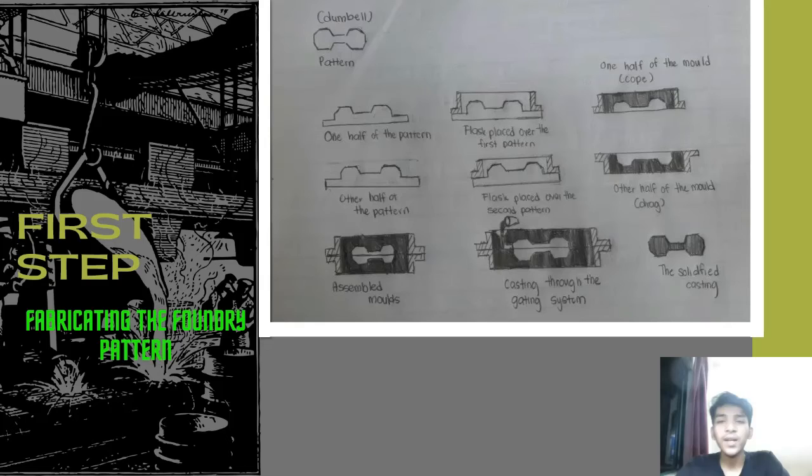The first step in the sand casting process involves fabricating the foundry pattern, the replica of the exterior of the casting for the mold. These patterns are often made from materials such as wood or plastic and are oversized to allow the cast metal to shrink when cooling. They are used to create the sand mold for the final part and can potentially be reused depending upon the pattern material. Oftentimes, two pattern halves are separately created, which provides cavities when put together.